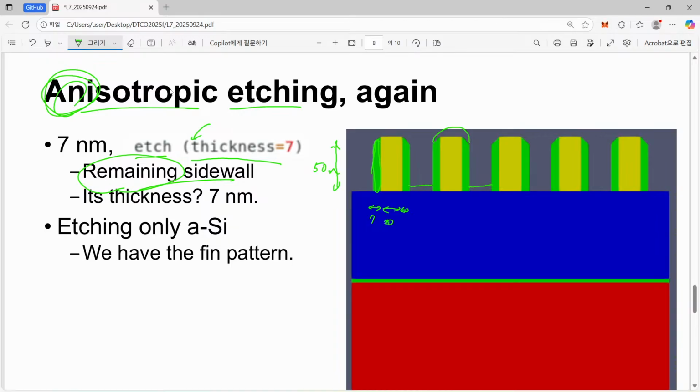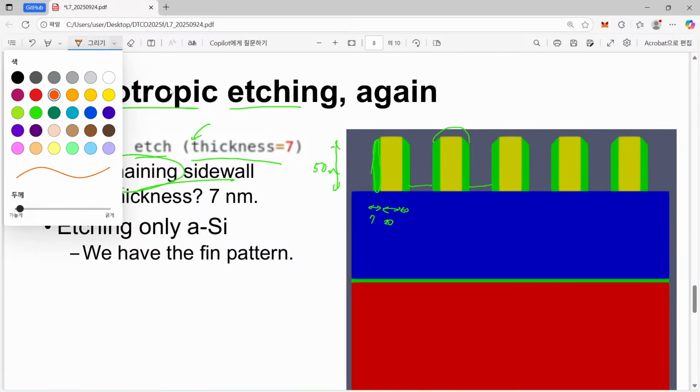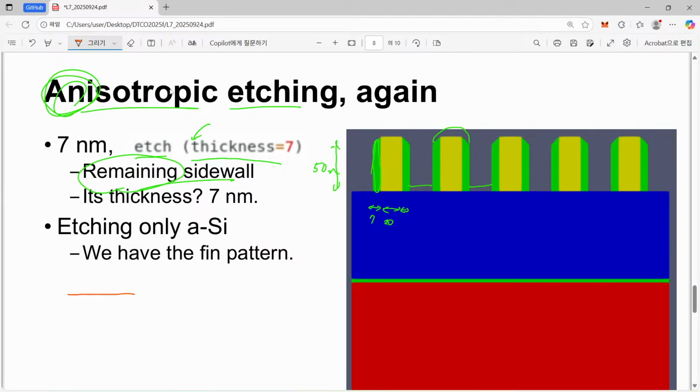And let's talk about the impact of trimming. At the beginning of our drawing of a 54 nanometer pitch, let's assume that we become quite lazy. Oh, just do 50-50. So we just draw a 27 line and separate by also 27. Yes, this is 27 and this is 27 and also this is 27. Let's say that this is our original structure.